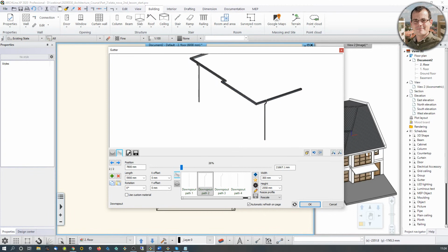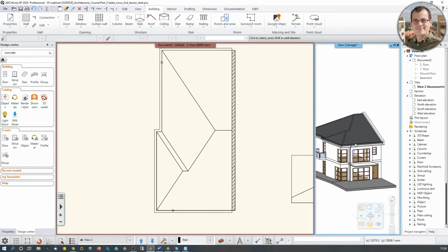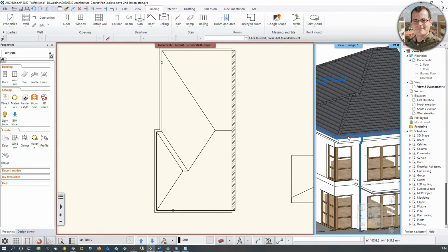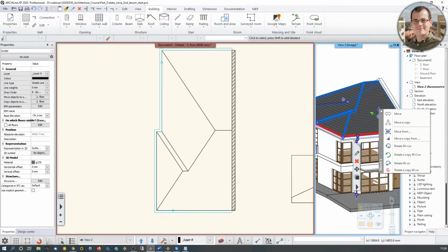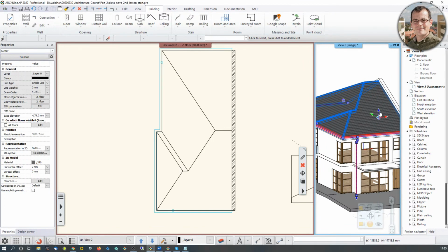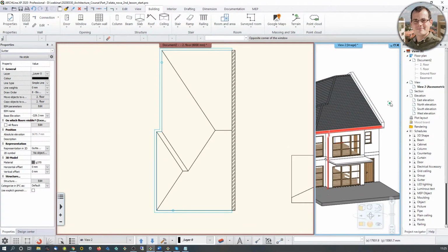It's very nice. So I'm just going to hit OK. And the downspout is now created. If I made any mistake with the sketching, for example, that whole scenario is way too high, then I just click on the marker over here, start moving the downspout, the rain gutter downwards, and add in the new value, 100 millimeters downwards, or maybe 200. I think that wouldn't hurt. 150, I think that would be better. So there you go. That's how you create it.